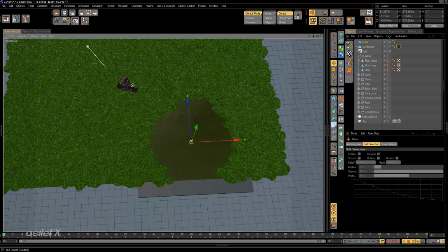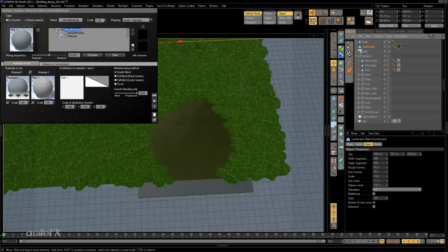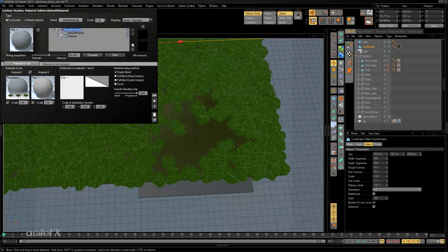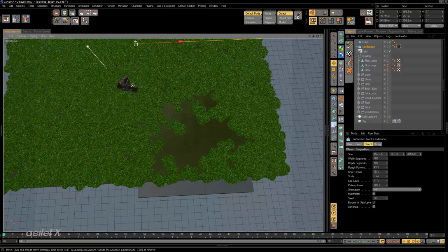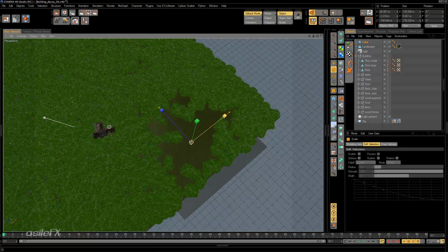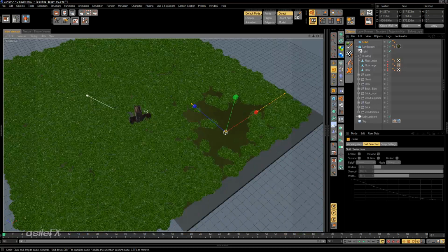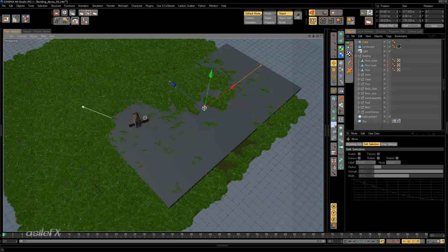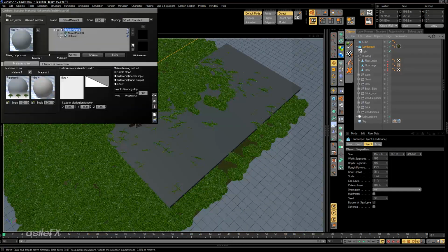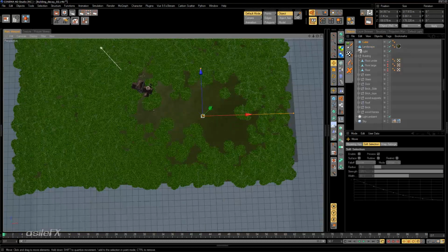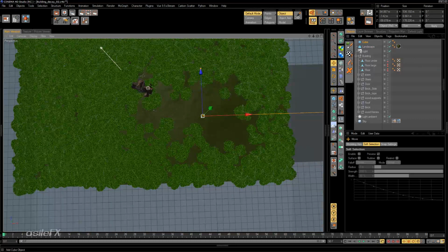And then if we go back into the populate objects, we can control the smoothness. So we can smooth it out on the edges if we wanted to adjust our transition. If you want to see how the different scales work on different axes, we can scale it. I'm going to scale it on, for the object mode, kind of move it over. We'll take a look at it first. Go into the landscape, populate, and move that under, and now we can see that it is stretched out properly. So we can stretch it out even more.